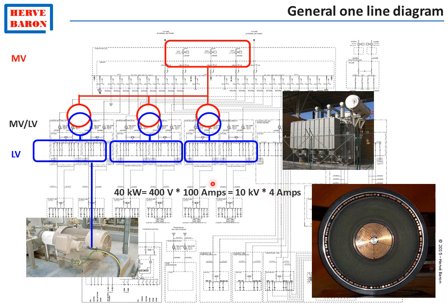This is the reason why transformers are used, so that electrical power is only carried by large cross-section expensive cables at low voltage over a short distance, and electric power is carried by medium voltage cables like 10 kV cables over a long distance.